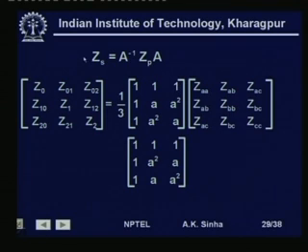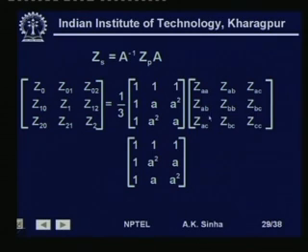Now, we have for this system the phase values as ZAA, ZAB, ZAC, that is, the mutual terms ZAB between A and B and ZAC between A and C will be there. Similarly, this will be ZAB, this is ZBB. ZAA, ZBB and ZCC are basically the self impedances of these three branches, and AB, BC and CA are basically the mutual impedances which are involved.